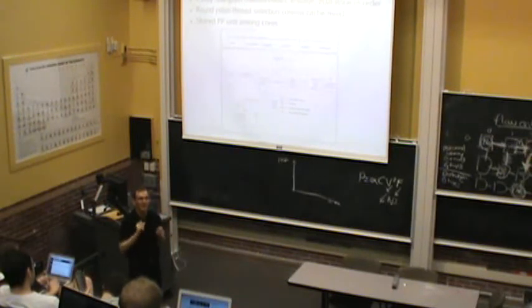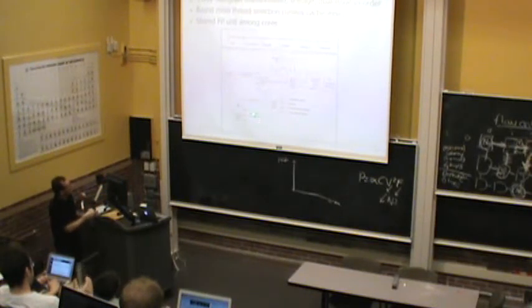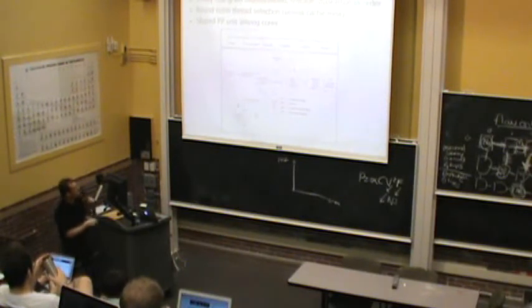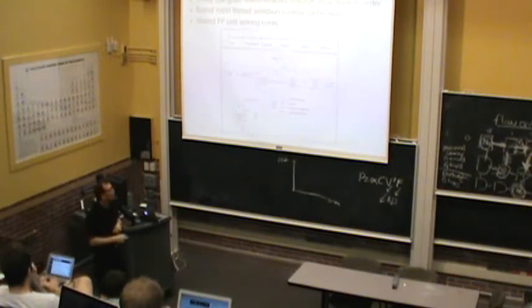Fine-grained multi-threading eliminates branch prediction, right? And you can see what fine-grained multi-threading actually adds. This is kind of like your exam question in the first exam, right? You have the iCache, and there are program counters, 4 program counters, and there's a thread select mux that goes into the iCache, and there are instruction buffers, and you have 4 register files. There should be a mux somewhere over there, which is not shown here. And there's a thread select logic that selects which thread should go next. And normally, if there are no cache misses, you round robin across the 4 threads.